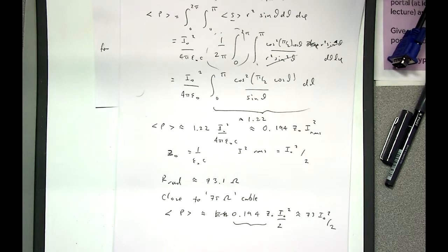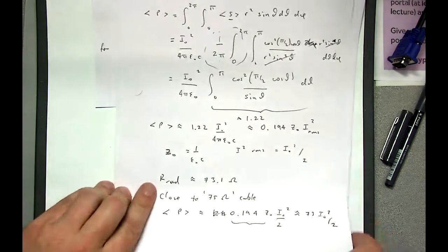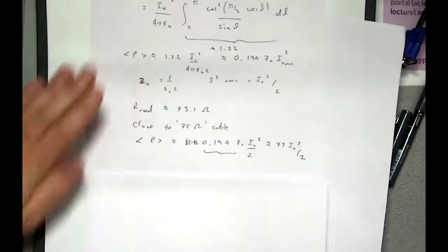So how can we use that calculation in a useful way? So we said, imagine the Winter Hill transmitter, we had something like a 100 amp feed, right? And we had about 500 kilowatts emitted for a quarter wave antenna. But we saw we didn't really get that because the resistance was actually smaller, so we only got maybe 100 kilowatts emitted for 100 amps. We'll turn that calculation round, and just to finish off,